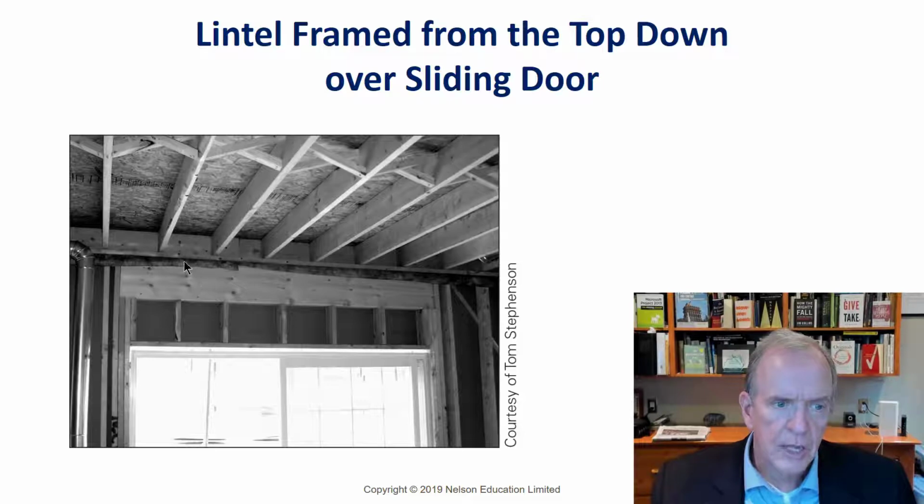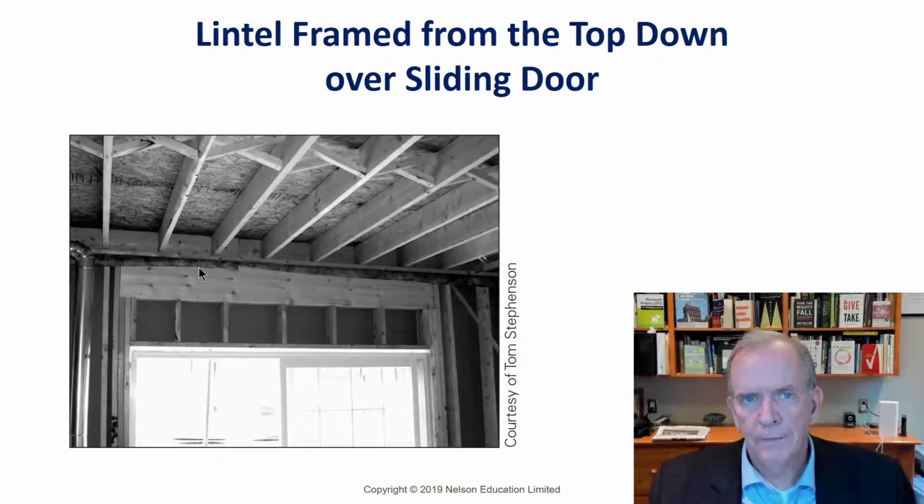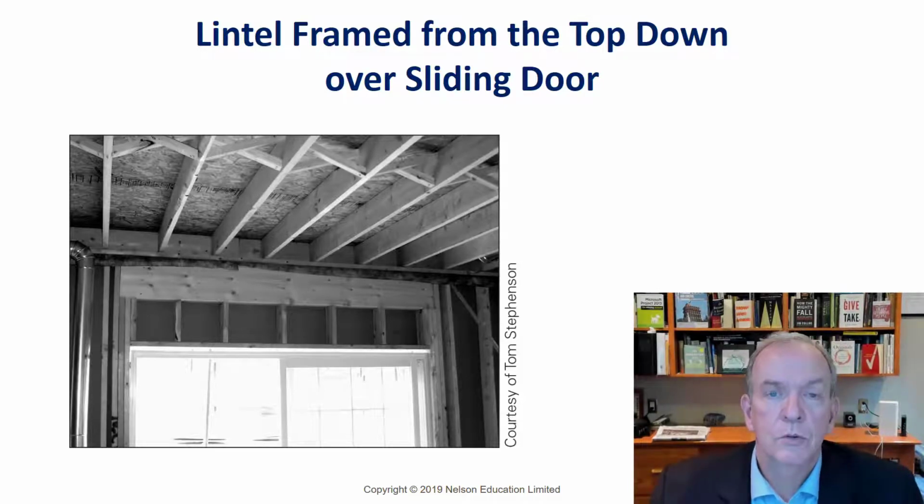And this is actually a weather barrier material. It's a Tyvek material, and we'll talk about that in another class, but it prevents moisture from coming in, and it allows any moisture that's on the inside to breathe out to the outside. But that's a little bit more complex issue that we'll get into when we start talking about the building envelope. But in order to be effective, we have to put this in during the framing process, because it has to wrap around as we build things. And so that's exactly what's going on there.